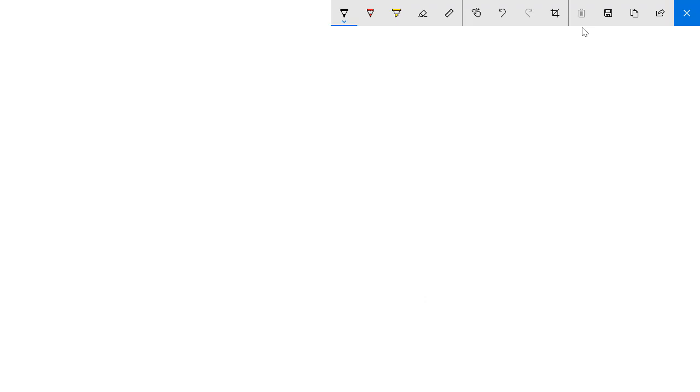So based on that, we derived a few equations out of it. We know that gm, we just derived it from the last page. So gm equals to beta n (VGS minus VTHN).